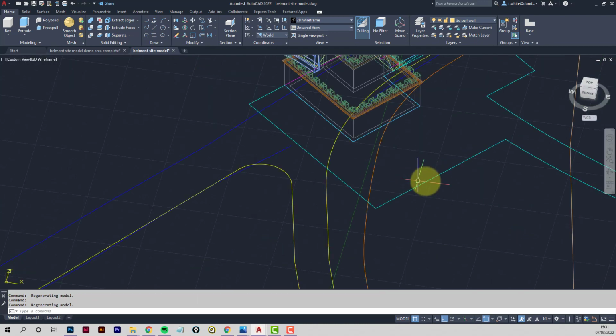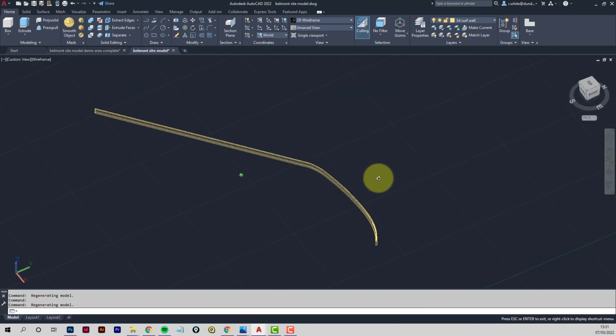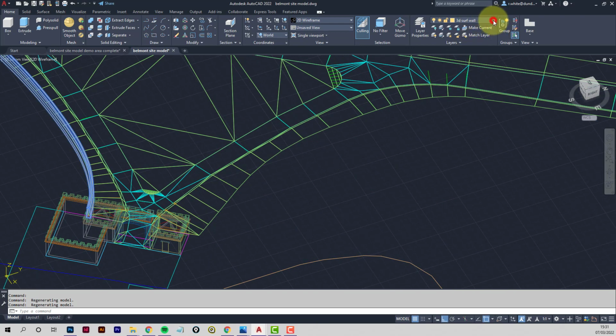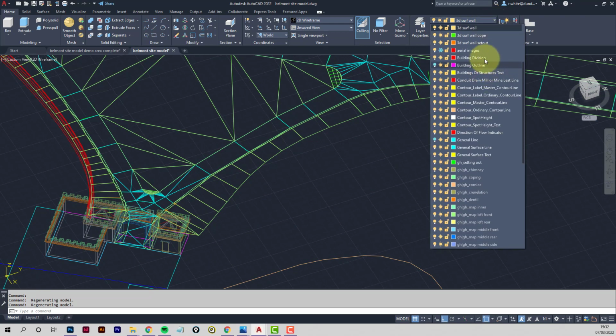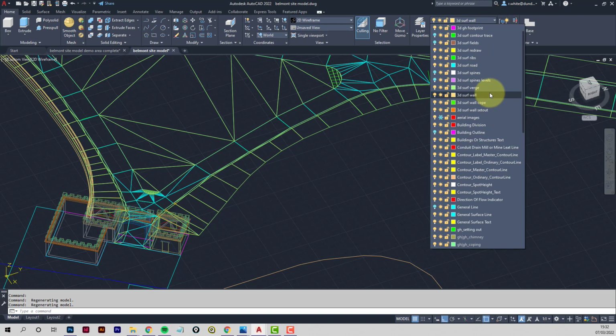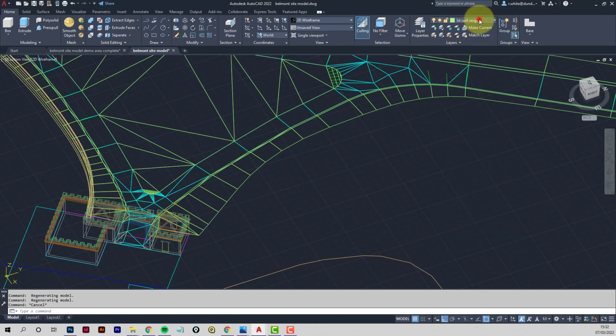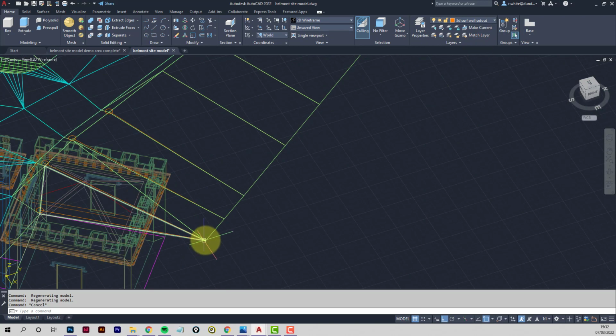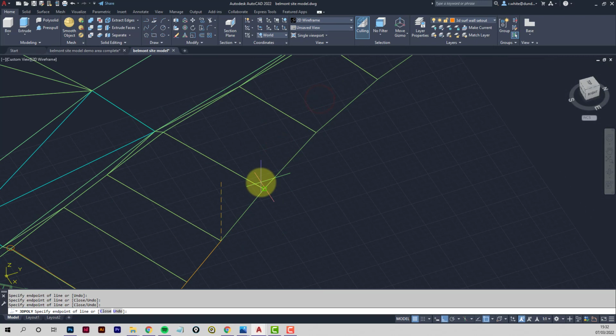So what I'll do is I'll set up the guideline first for the wall. And so this is a bit of a different object, one we've probably not encountered before. That's a 3D polyline. So I'm going to use this layer, wall set out. So a 3D poly. Okay, and I'm just going to pick up the ends of all of these bits of the ground.